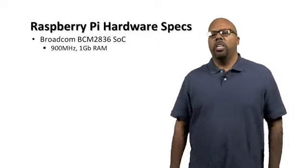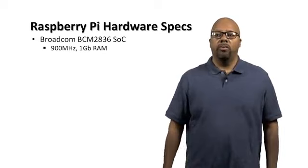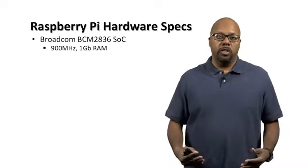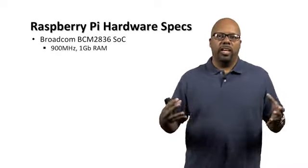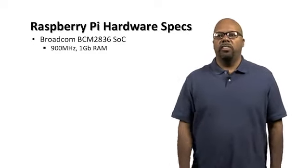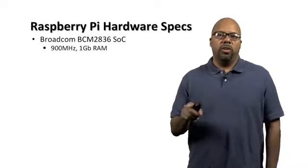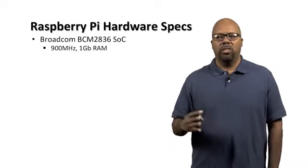Okay, so it's a Broadcom chip, the microprocessor. The chip, the integrated circuit, is a Broadcom SoC. SoC stands for System on Chip. It means that it's got a processor and it's got other things on it that make an entire system. So you take a system, you put it onto one chip. So System on Chip, that's what it stands for. But it's a BCM2836. Now, the previous Raspberry Pis had BCM2835, which is slightly slower.